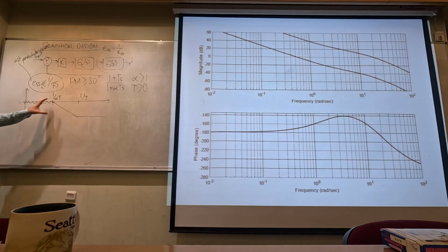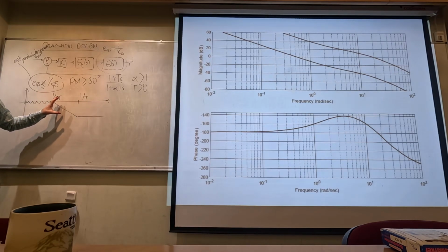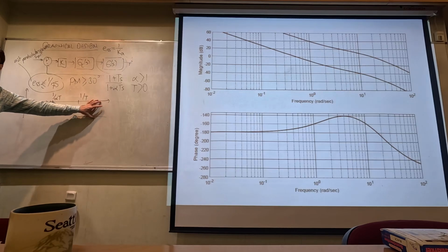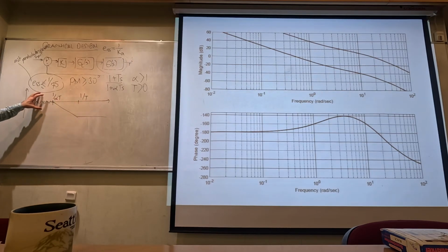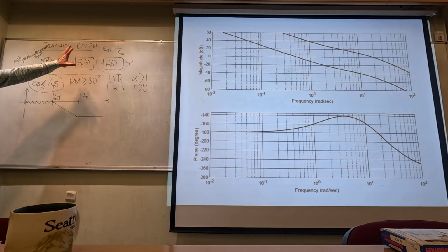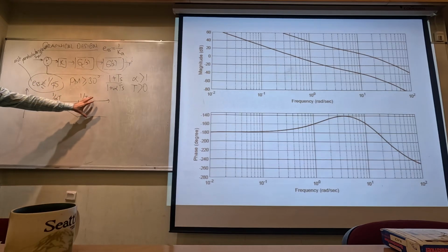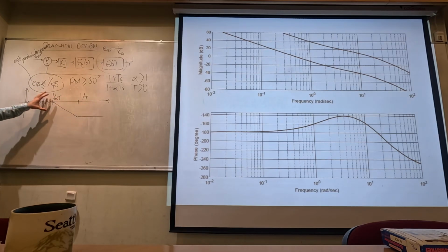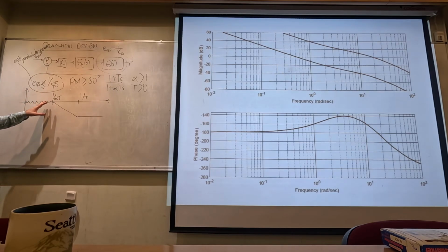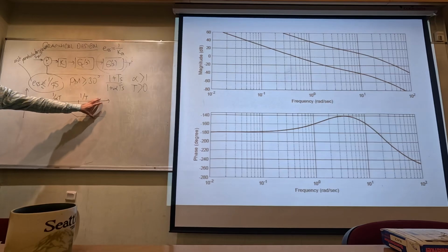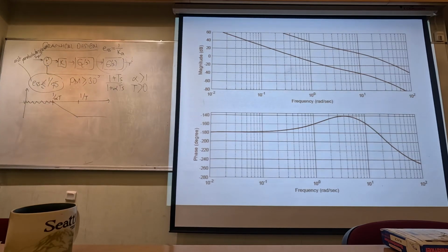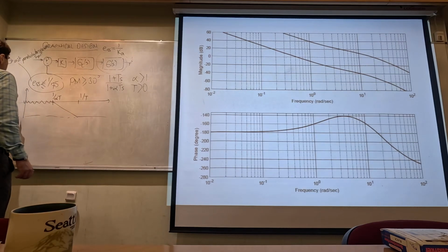As you see, when I add it to this system, this compensator reduces the gain at high frequencies, but keeps the gain magnitude the same at low frequencies. So steady state error performance will not change, but I can play with the gain amount here to change the actual phase margin of the system. Okay? So here, what is this magnitude here?